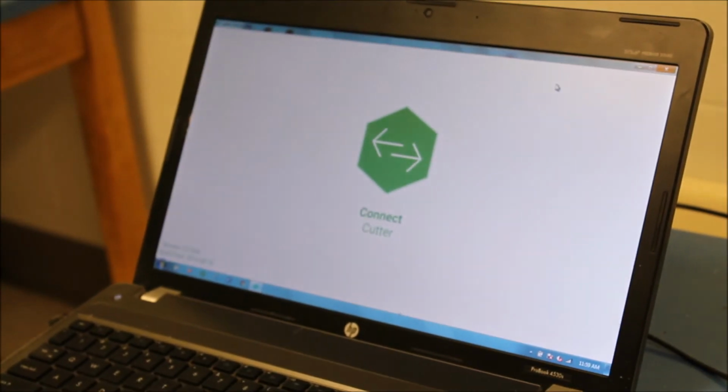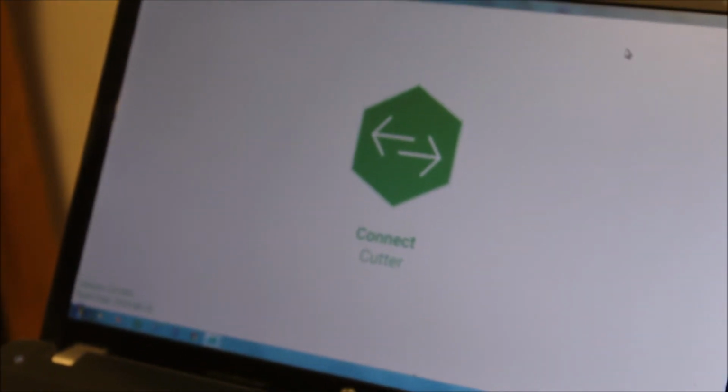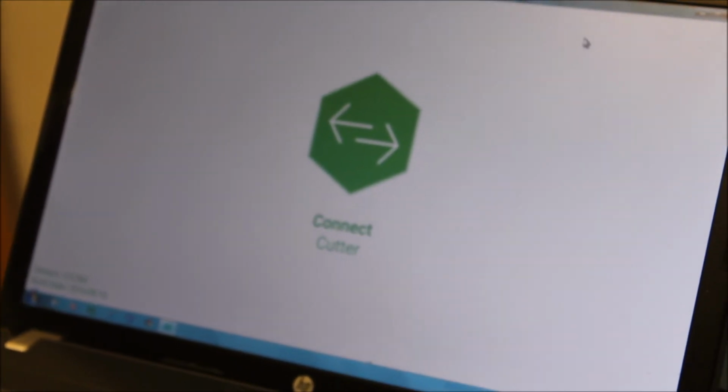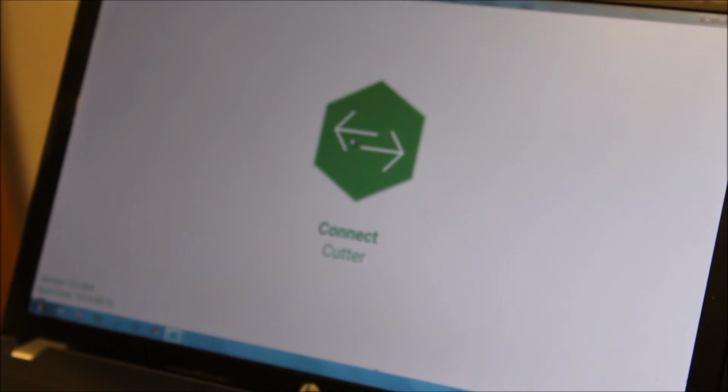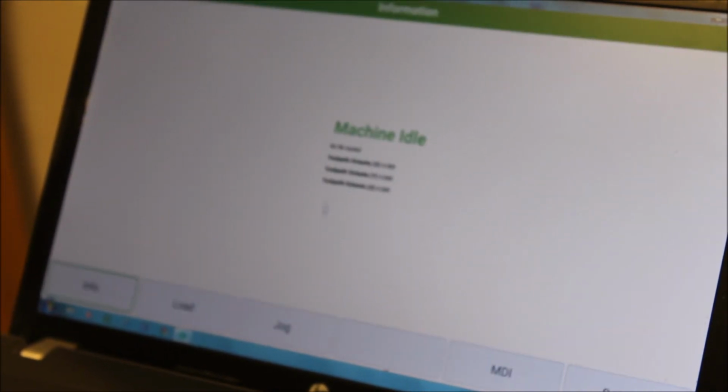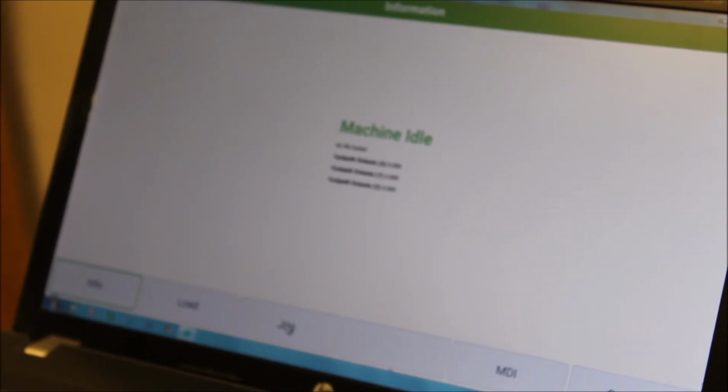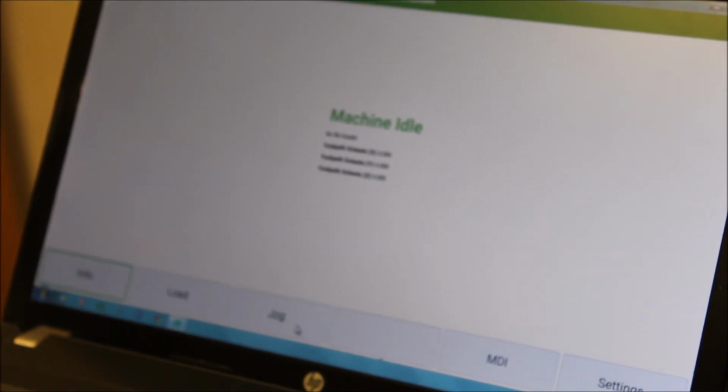because then you'll run into the clamps and have trouble. So the first thing you're going to want to do, once you have the G-code saved, you want to transfer it to the Shapeoko and open Carbide Motion. Click Connect Cutter, that's going to be the first page you see, and you're going to want to home the machine. So go down to the 3rd tab over, click Jog, and click to begin homing.